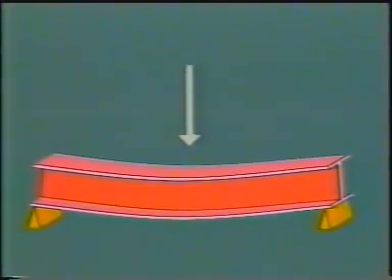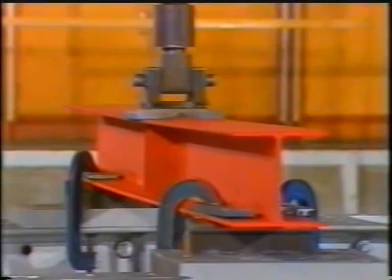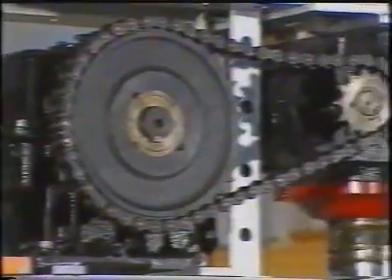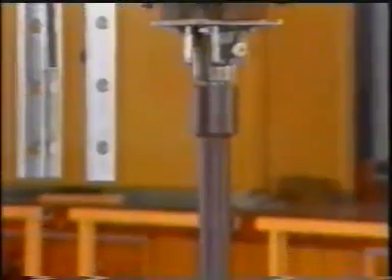The next three tests all concern simply supported beams of varying slenderness. A central vertical load, causing bending, is increased to failure in each case. The first beam is just over a metre in length and can be described as being short and stocky. The load is applied to the beam by a screw-jack device via a vertical rod.